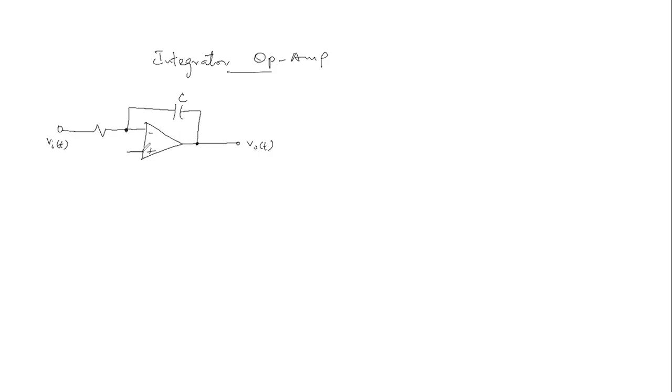And then the non-inverting terminal is connected to ground. So let's get this to ground. Where this is the reference voltage, which is 0 volts, meaning a ground connection. This is the non-inverting voltage, V sub P, and the inverting voltage, V sub N, which are node voltages.